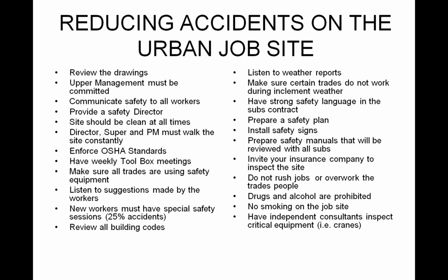Obviously, OSHA at a minimum has to be enforced. And a good work site is one in which there's no fear from the workers to go to the safety manager or the project manager and say, hey, I think there's an issue on the third floor. It doesn't look like the railings are quite solid. There's no toe board. We've got rips in the fall protection. It should be a site where you feel comfortable in bringing these things up, and you're not going to be looked at as a troublemaker for making more work for the safety person. So that has to be built up on the site as well.